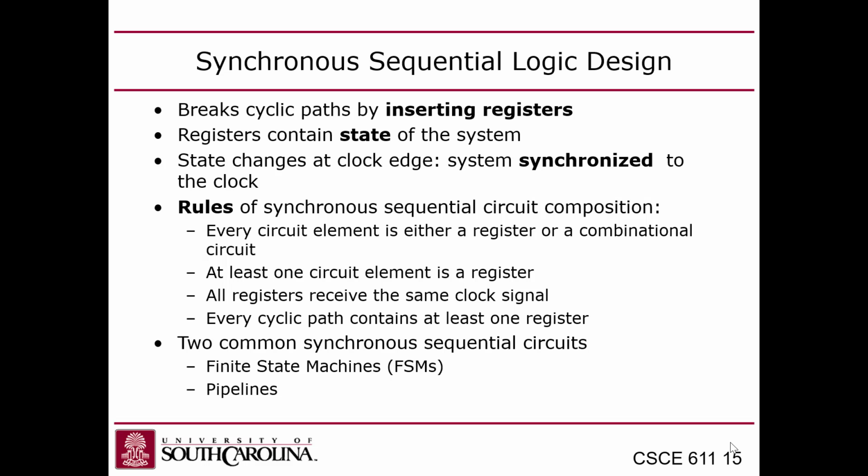We will be creating a pipelined CPU in this class, but we're also going to be designing a finite state machine in the next lab because there's a step before we get to the CPU. We're going to create a calculator on the FPGA, a reverse Polish notation calculator, and for that we're going to use a finite state machine. You guys know what an RPN is? Have you ever heard that? Reverse Polish notation. So that's the calculator with a stack in it.